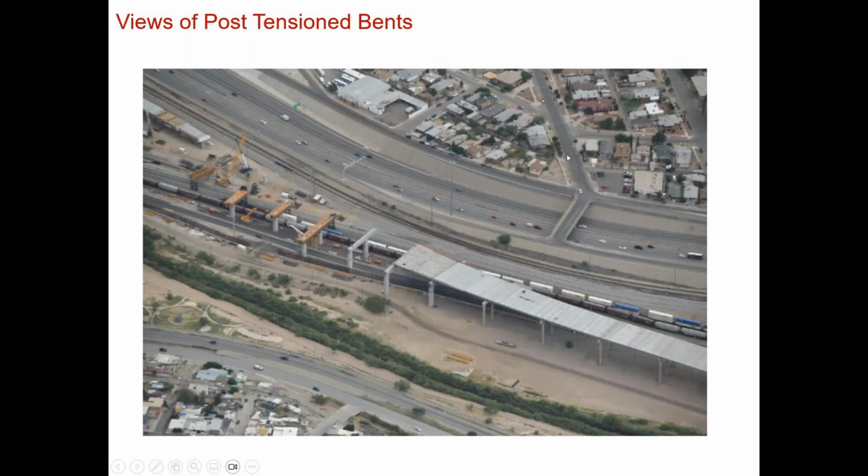Usually these types of bents, you can face them on multiple occasions in projects. Whenever you have a bridge under design that crosses over a railroad or crosses over a roadway, you can end up with a situation like this, where you have multiple locations where the substructure of the bridge conflicts with the roadway or the railway underneath it, and you end up doing multiple straddle bents to make sure that you can still place your columns around the road and respect all the clearance requirements from AASHTO guides and codes, and from the railroad authority as well. So that's where you are likely to see this type of construction, those post-tension straddle bents.